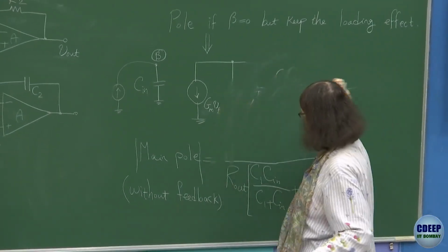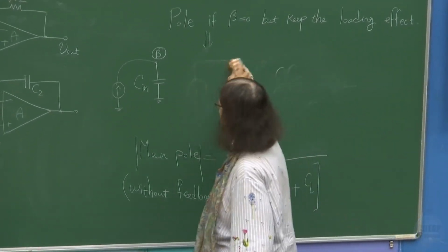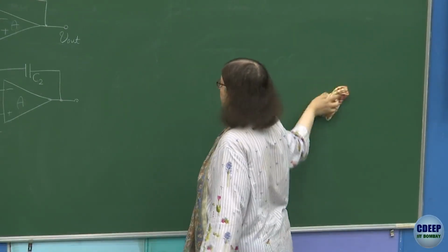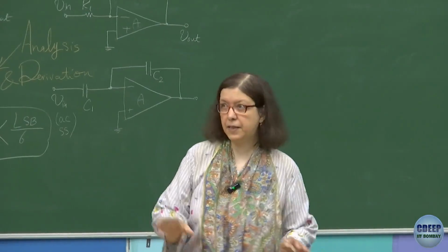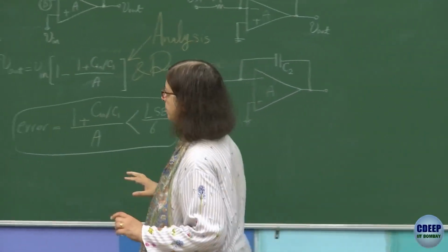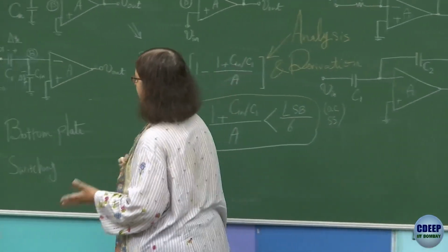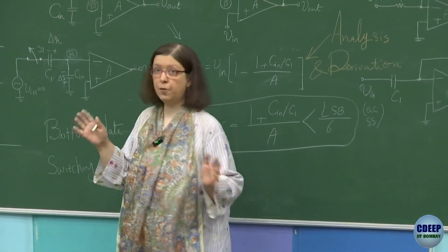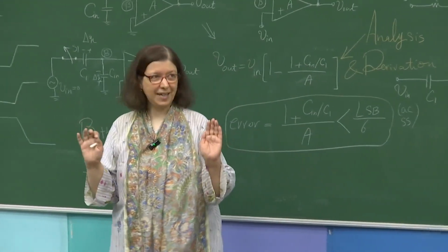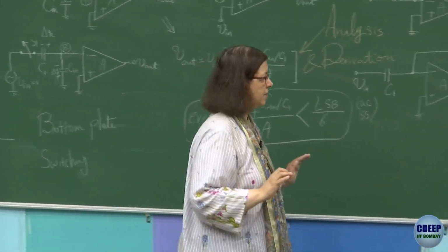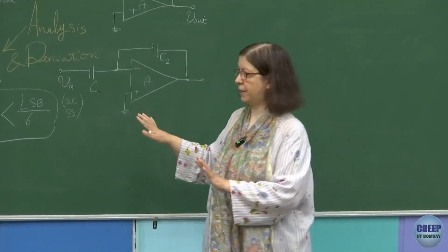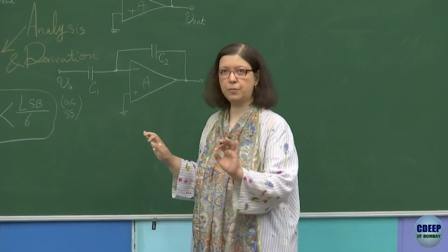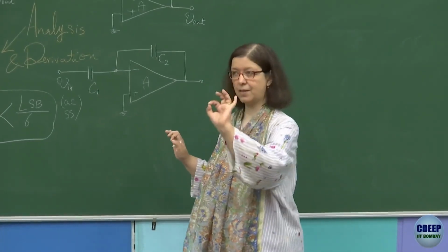Now we have a pretty good idea about this effect of Cin. See, for example, Razavi has explained how the charge injection effect gets cancelled or compensated and goes away, in almost one page, very nicely with details. My suggestion is that you first analyze it the way we have analyzed in the class, using bottom plate sampling, a generic and universal circuit.